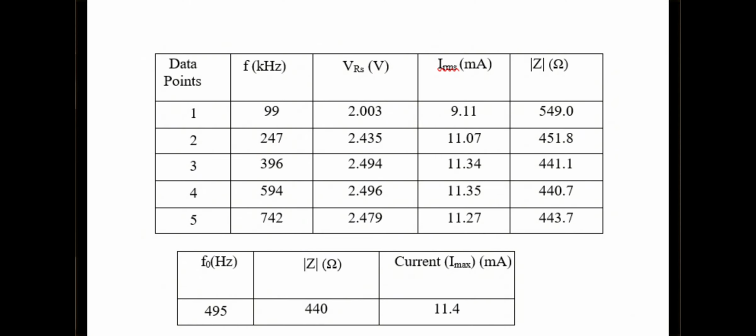After that, I added an extra resistor in series with the same circuit, without changing anything else in the setup, and measured the voltage at the same frequencies to observe how increased resistance changed the resonance.